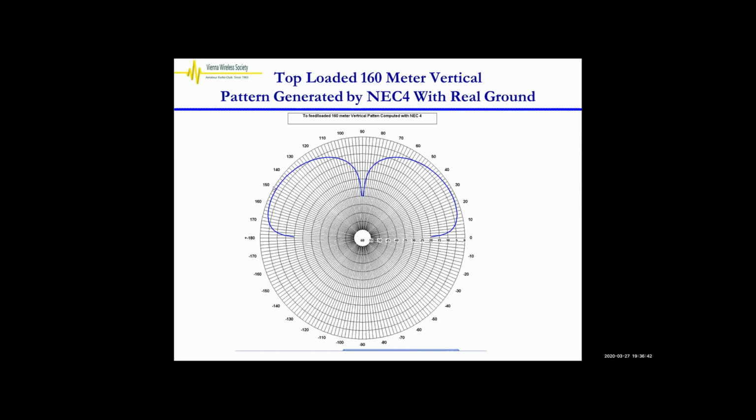So again, my peak gain is a little bit below isotropic, but it's probably about -1.5 or so dBi. So this code has more accuracy dealing with radials close to the ground than the other ones. But as you can see, the mini NEC code is pretty close.